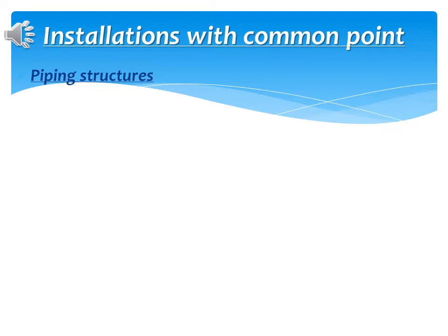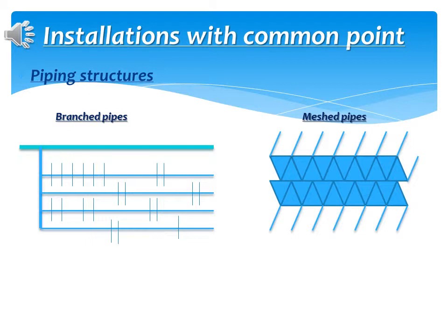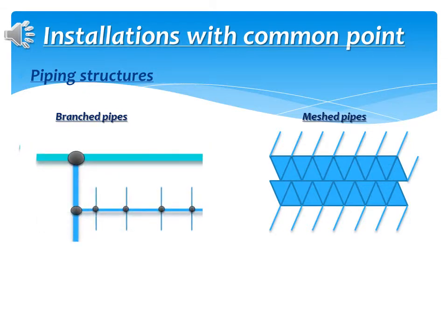Pipe networks can be seen in all factories, houses, installations, etc. There are 2 types, branched and meshed. Branched networks are easily solved compared to meshed ones, according to the method previously applied; it only increases the complexity due to ignorance of the directions of the flow. Meshed networks cannot be solved by direct methods. In many places we have no idea of the direction of flow; however, they have advantages over branched networks.